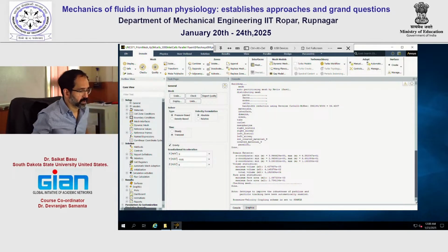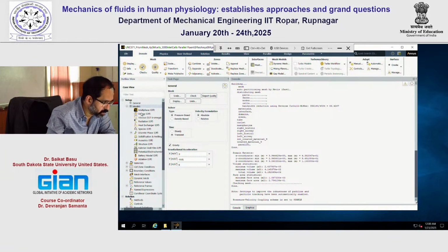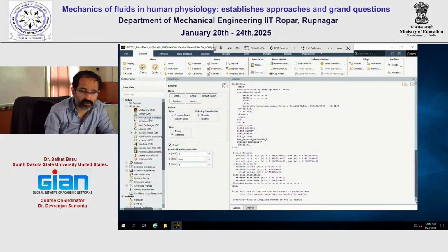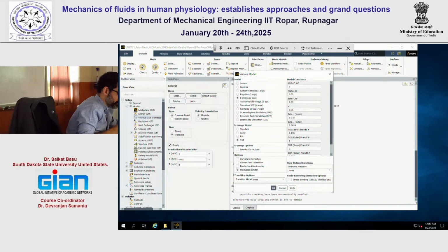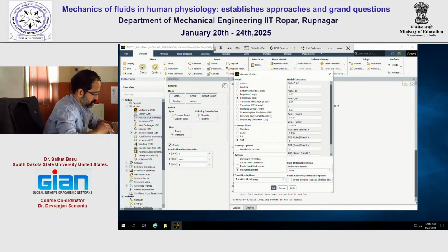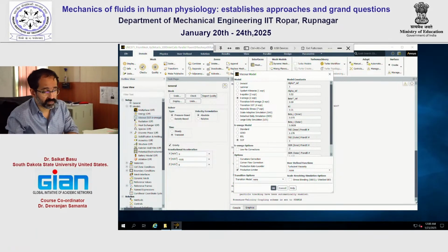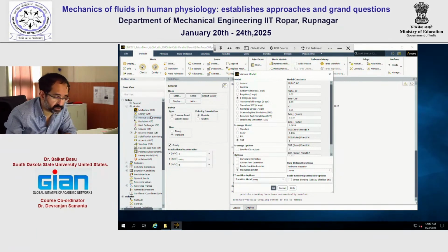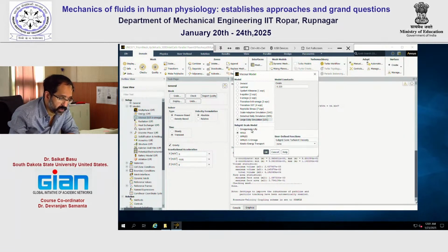So this is all for the general model. Let's now go into the fluid mechanics modeling. We are going to set it up as an LES model, so viscous, not SST k-omega. I do remember the individual numbers, but just in case, I don't think I have the protocol here either, so that's fine. But you will find the relevant parameters that you have to set up for the LES simulation in the protocol. But over here, let's go to large eddy simulation. Now, what subgrid scale model would you use?